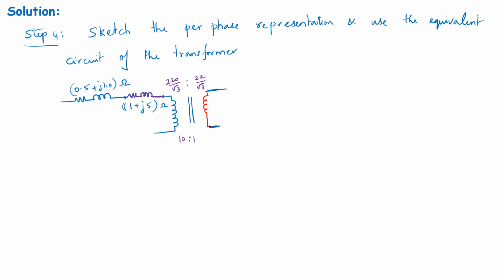And this secondary side of the transformer is now feeding a load, just one phase of the load. And what will be the current flowing in the system? The current IA is going to remain intact, which is 22,624 at an angle of 36.87 degrees in amperes.